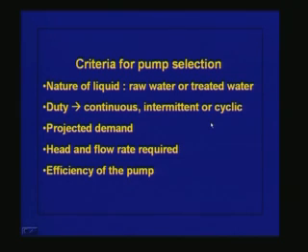The size of the pump depends upon the demand that we are going to meet, and we are going to design this pumping system not for the present use only, but this pumping system should be able to meet the demand even in the future. So the projected demand is another important factor in the criteria for pump selection. Over a period of years, as the demand is increasing, the pump should be able to operate and give the same level of efficiency even when the demand increases in the future.